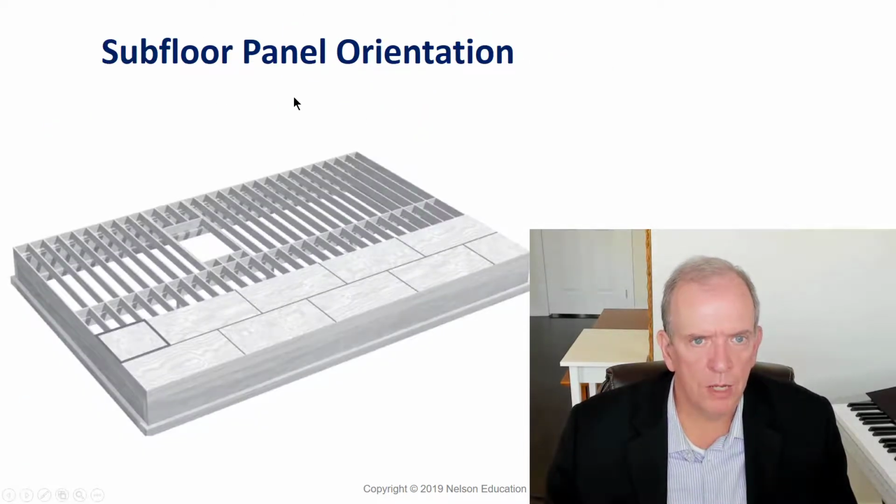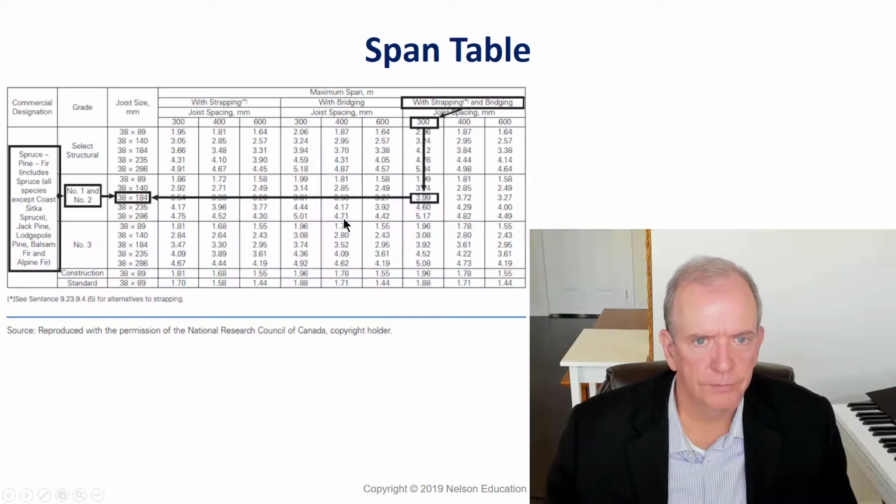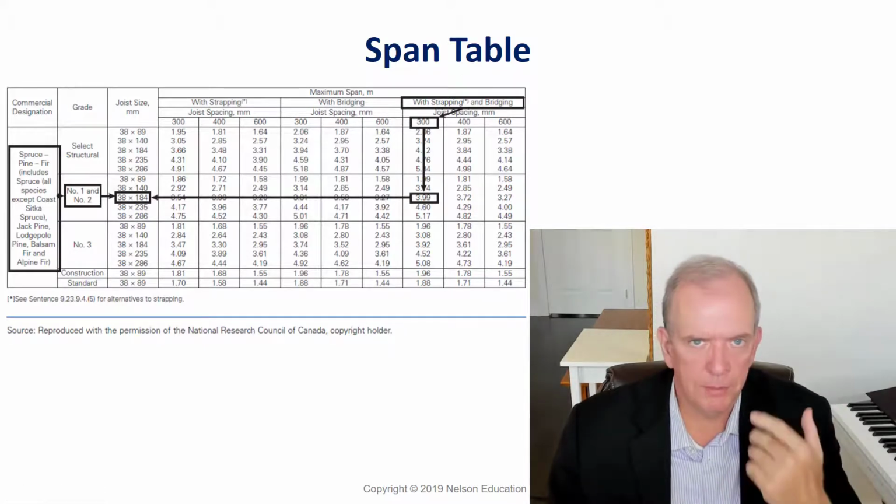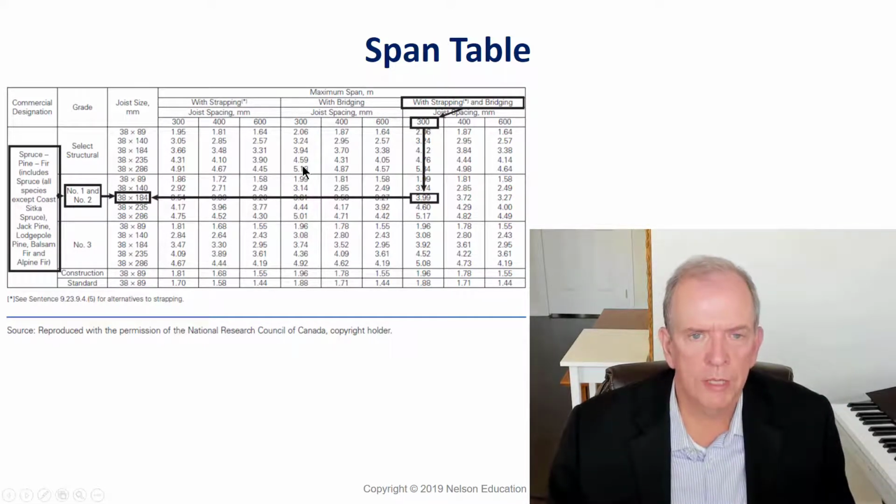And here's subpanel orientation, again, the lapping over that I talked about. Headers, trimmers, tail joists, regular joists. I mentioned the building code has a span table. So the span table is here. They have a number of predefined tables. They have beam tables, span tables for floor joists.